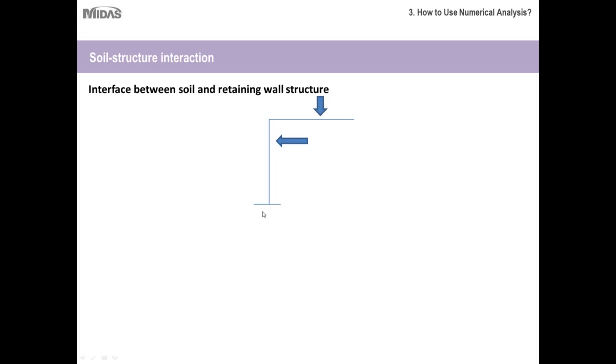So essentially it is nothing but a very simple stable system where you have one wall member, and this is the soil layer, and this vertical arrow is the surcharge, which may or may not be there, and this horizontal driving force, which is always there irrespective of the surcharge. This could be due to the unstable slope and the sliding wedge, or this could be due to the active earth pressure.